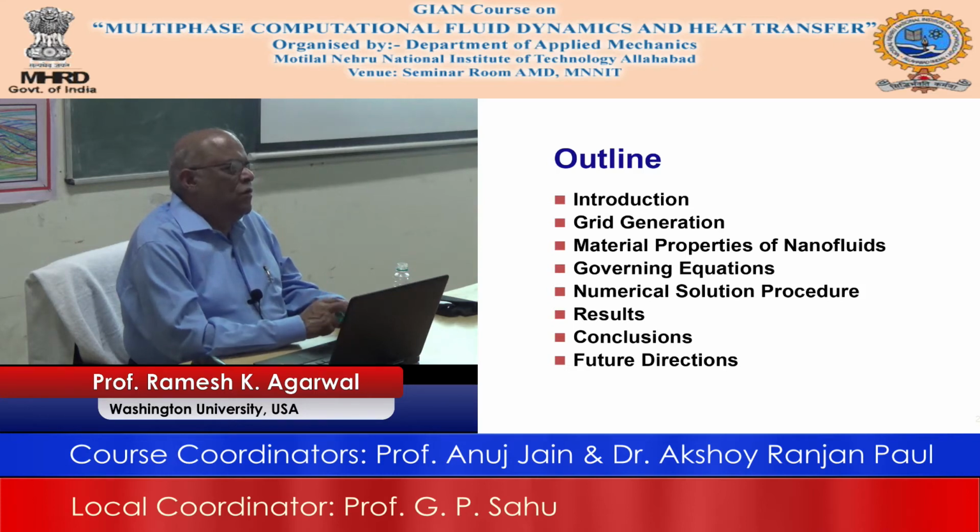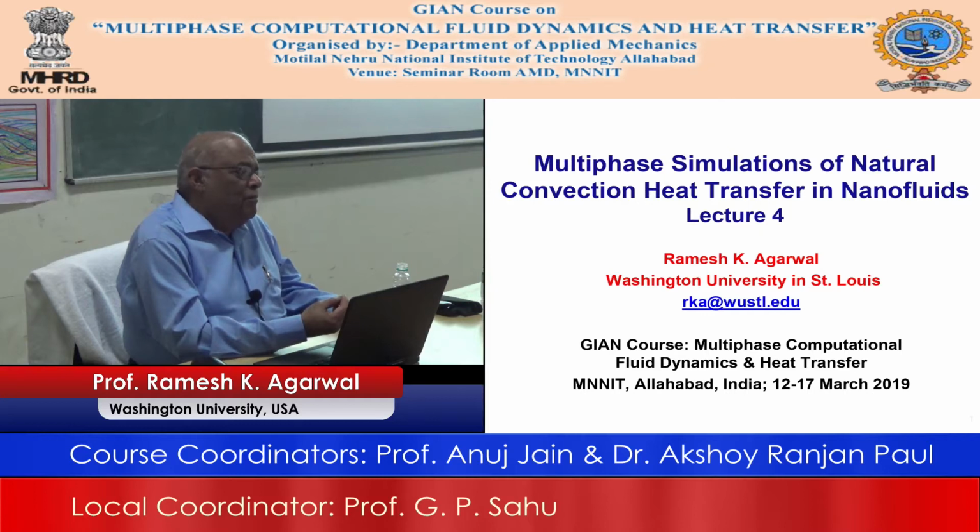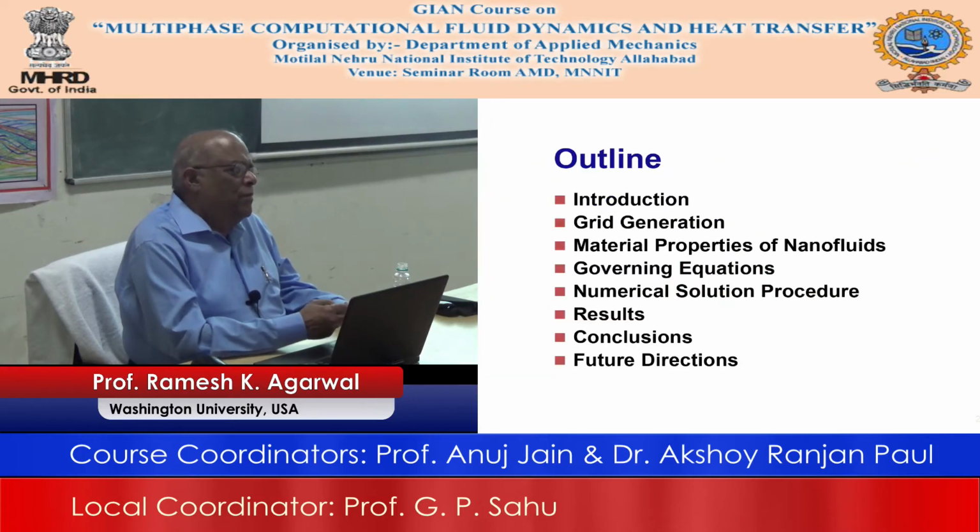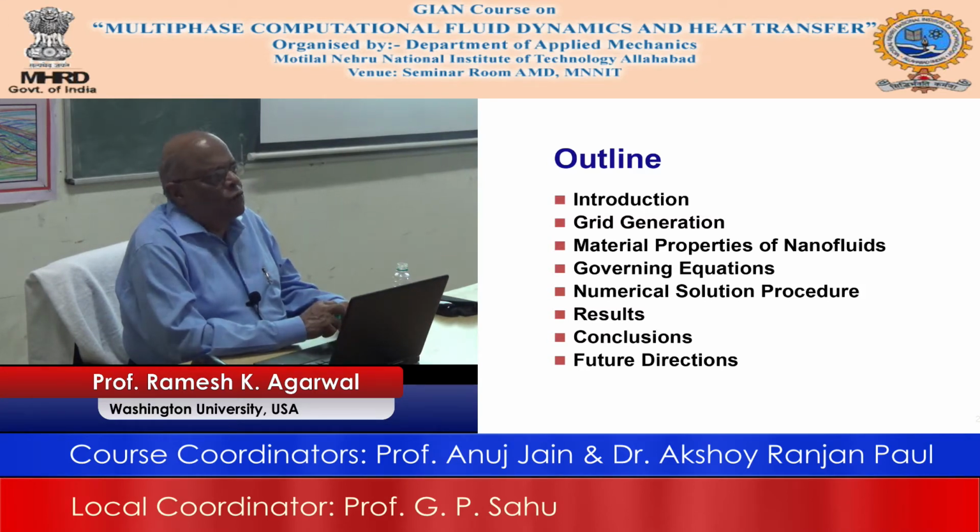So you can use it to heat up, or you can also use it to cool by increasing the thermal conductivity. And it turns out that by 2 to 4% addition of a nanoparticle, and you want to keep it small, and small means that you want to keep it at a micro scale, so that they almost float like a Brownian motion. You don't want to sediment them.